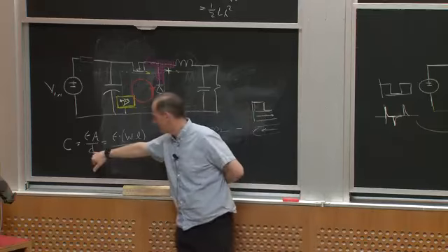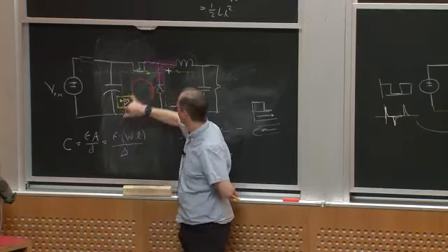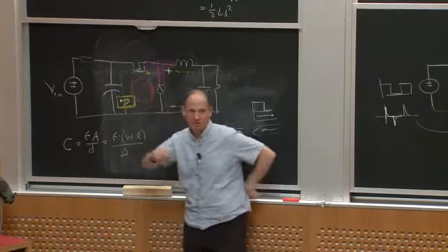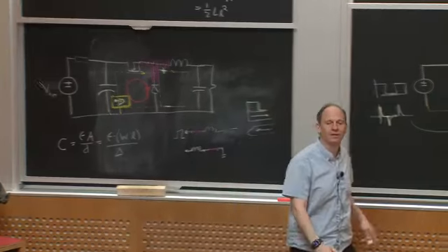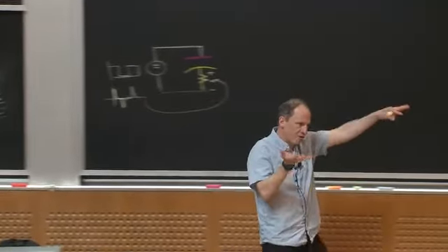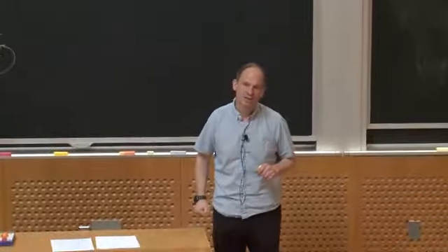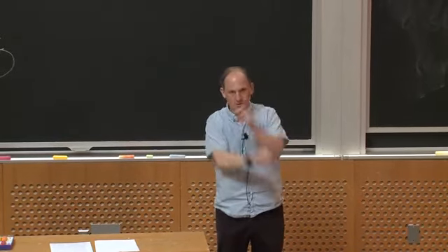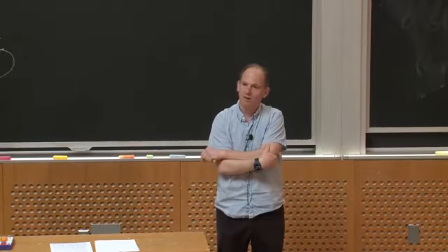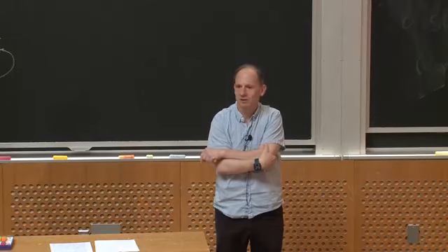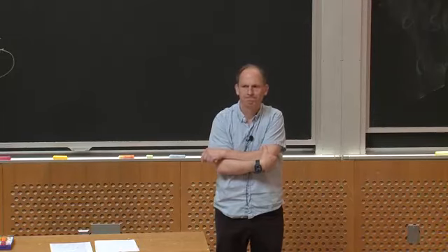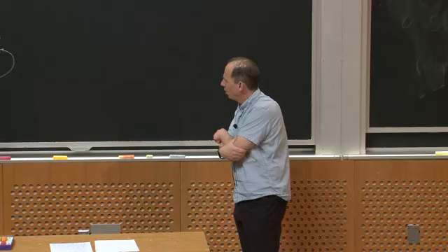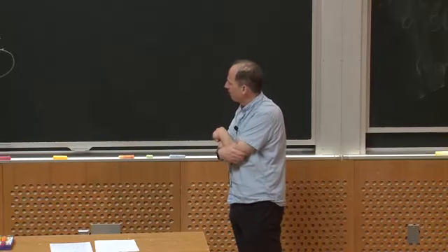Also, keep the distance between this thing and this thing bigger so that the capacitance goes down, right? So I can put them as far apart as I can practically do it, and reduce the areas, and that will help me minimize that capacitance that's causing noise. Does that make sense to everybody? What else could I do about that?